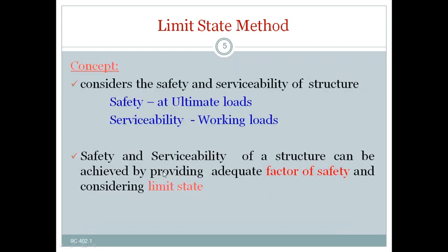Right. What is the concept of this limit state method? What is the concept behind this limit state method? In this limit state method, we consider the safety and serviceability of the structure. Generally, the safety at the ultimate loads and the serviceability of a structure at working load. That means the structures are designed by using this limit state method, or by using ultimate loads, and we check the serviceability of that particular structure under working loads.